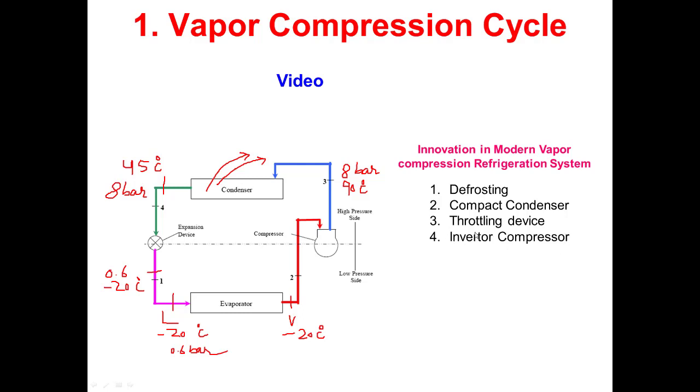the electricity is also very low, because if the temperature setting is low, then the speed of the compressor will be lower, hence the input to the compressor, the electricity consumed, will be less. While in the case of a constant speed compressor, the compressor has to operate at constant speed, so that means you cannot save electricity.